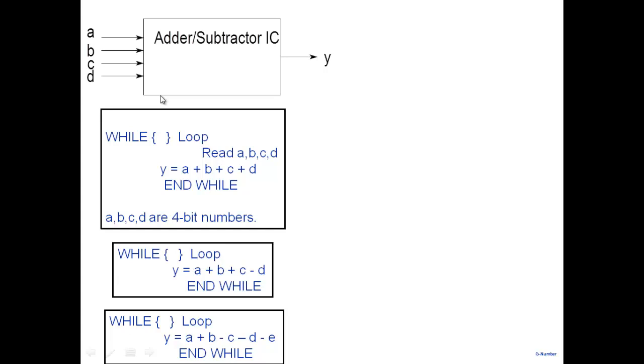Now, the alternative to that is, as I said, there are a variety of general purpose ICs available. You take them up and you connect them and customize it for your application. And the problem with that is the PCB space becomes large, weight and size becomes a problem. The delays are much longer, power dissipation will be higher. So all those issues are there, as a result of which you want to put everything inside one IC. So these are just, as I said, examples to illustrate that particular point.